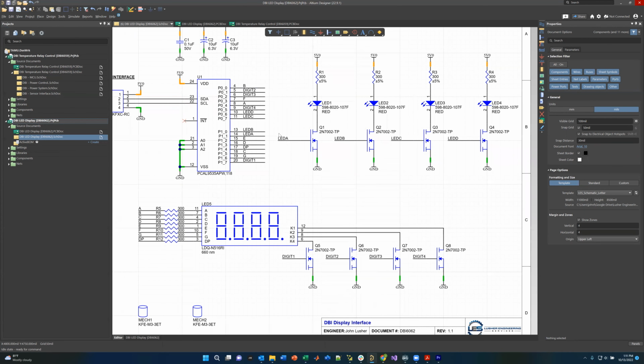Well, I could have used a massive connector and a microcontroller that had more I/O lines, or simply use a port expander. This takes in I squared C over this connector.